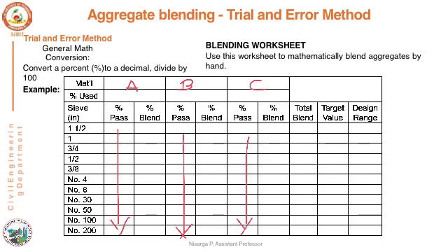Next we have to choose a proportion. How do we choose? Maybe I can take the percentage of aggregate A as 50%, aggregate B as 30%, and aggregate C as 20%. Whatever trial proportion we have considered needs to be written here, and then we continue with the calculation.